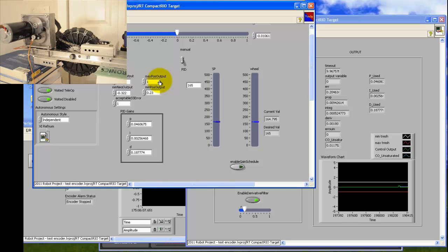You see that was, well, you probably didn't notice, but that was probably a lot quicker than what was happening before. And if you ever have trouble where when you do a short throw, it's not going, that's because your gains are so low that the PID controller is outputting something within your deadband. However, this is great. This controller, I'm pretty happy with. And so I would probably push this to do further testing with on an actual robot, run it in its environment, and see how well it holds up.